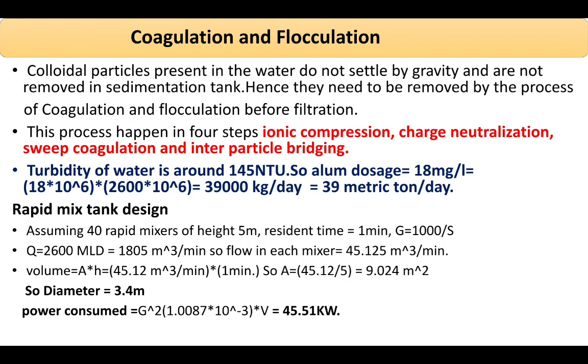So now comes the coagulation and flocculation part. Mainly colloidal particles present in the water do not settle by gravity and are not removed. So we need to remove them by the process of coagulation and flocculation before the filtration process. This process mainly happens in four steps, as you can also see here: ionic compression, charge neutralization, sweep coagulation, and interparticle bridging.